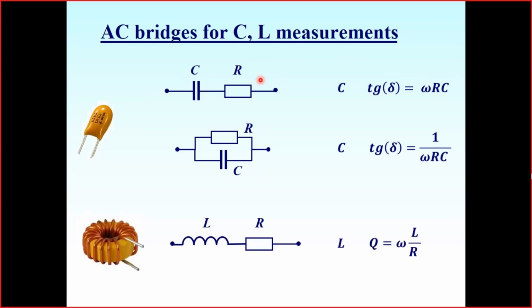Well, the same is in force with chokes, with inductive elements, and here it is quite straightforward to add the resistance of the wire itself in series with the inductivity. So using the equivalent circuits, we consider that the capacitors are ideal, so there is no DC current through them.